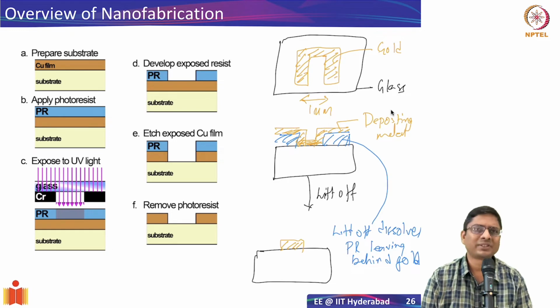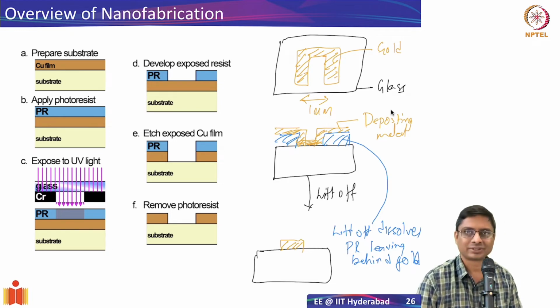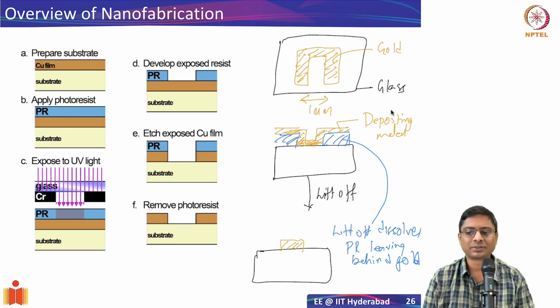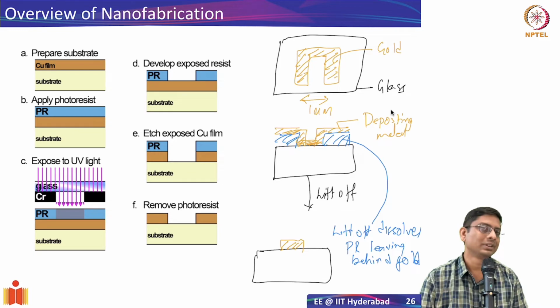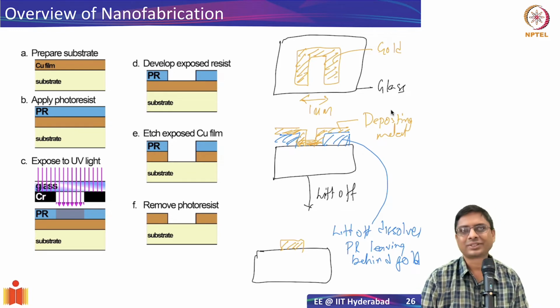So they tried 157, it didn't work out. So finally now they have come to EUV, which is not at all power efficient. And it's a big bottleneck. So instead of using this, why don't we go to electron beam? That's a question, right? The problem with electron beam is it is a raster scan.